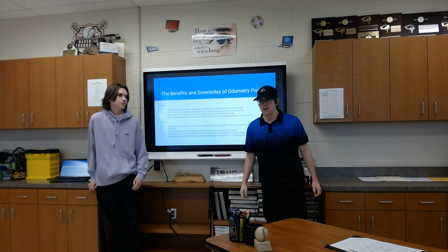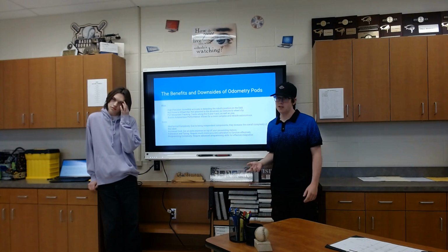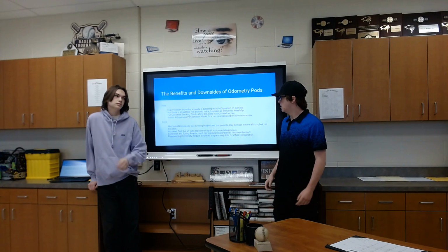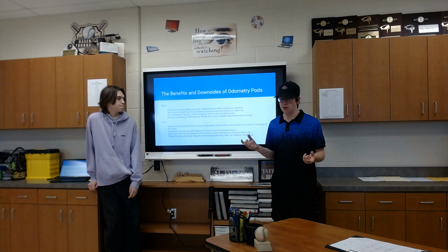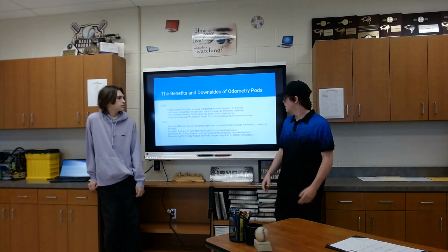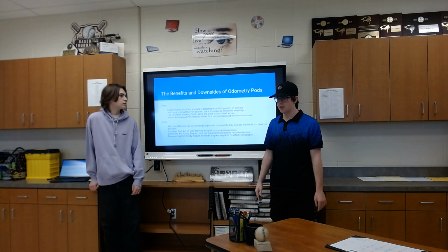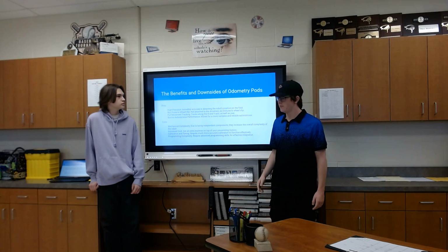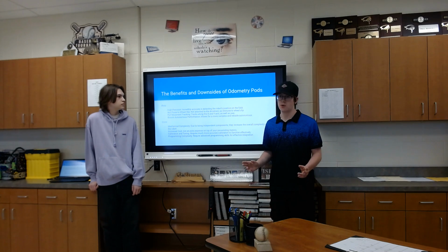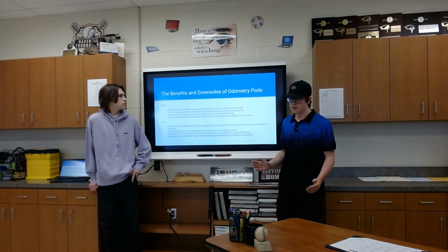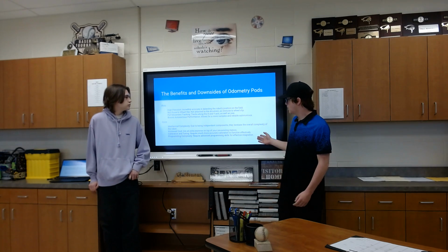The benefits and downsides of the odometry pods. They're high precision, so they're much more accurate. They're not prone to wheel slip, as I said. They're not attached to your current motors, so they're their own thing. They track the X and Y axis as well as the yaw, and overall they make your autonomous much more performant and accurate. The cons are there's mechanical complexity.